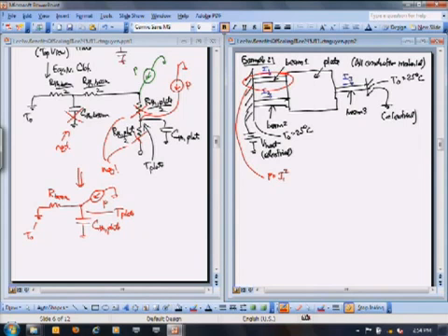denotes electrical resistance. Okay, so now you have to do some bookkeeping here. You've got two types of resistance. You have an electrical problem where you're sending current down an electrical resistance, but you also know that there's another resistance associated with that beam, and that's thermal resistance. They're just related by different constants. One of them is using thermal conductivity, one of them is using electrical conductivity, but it's all very much the same concept. But you have to bookkeep which resistance is which here. One of them is putting power in, the other one is dissipating that power.